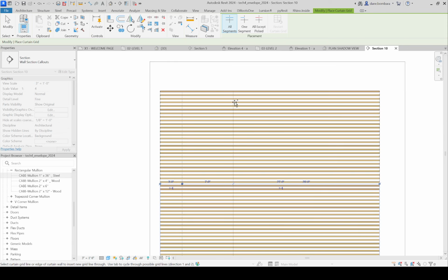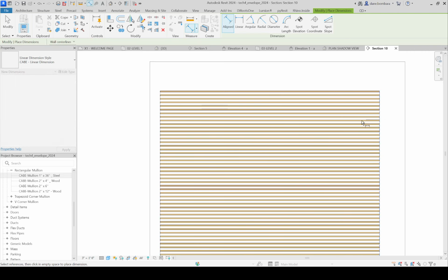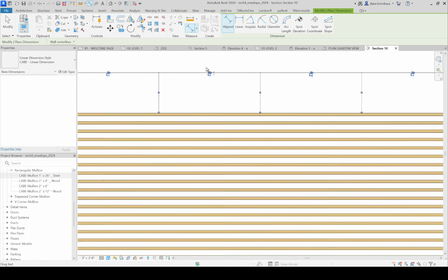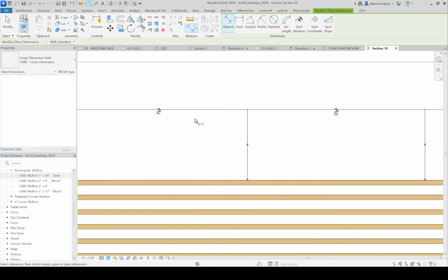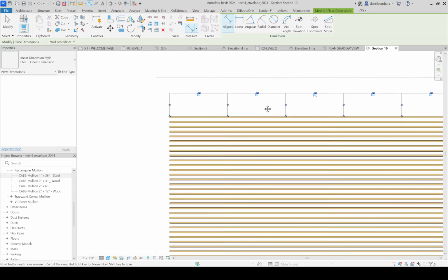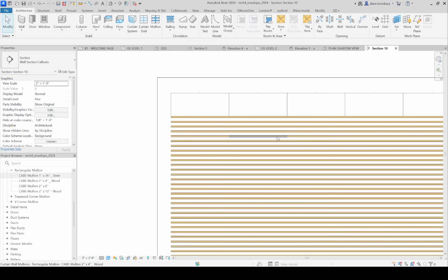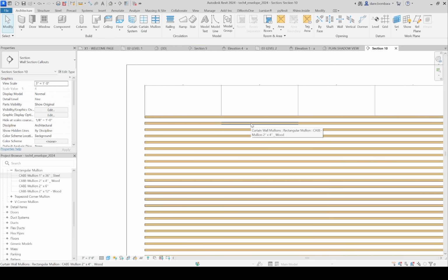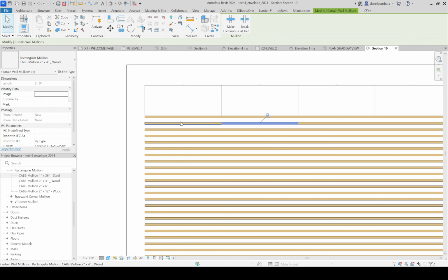It just adds the ability to put a mullion wherever I place it. So I put one there, put one here, place a bunch of them, and then, if I was being conscientious, I would make them good dimensions. I made them all equal right there, so they're all now 6 feet wide. So nothing theoretically changed. The only thing that actually changed is that now my horizontal mullion doesn't go all the way across the wall. It stops at the vertical grid because I can add a mullion at that vertical.